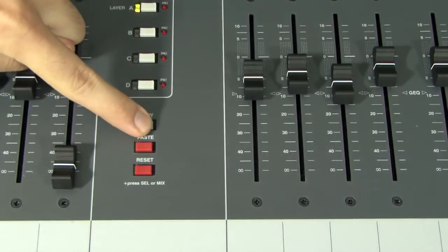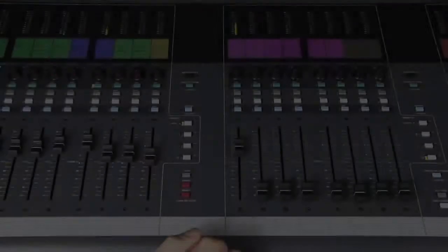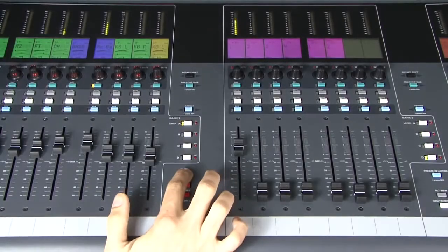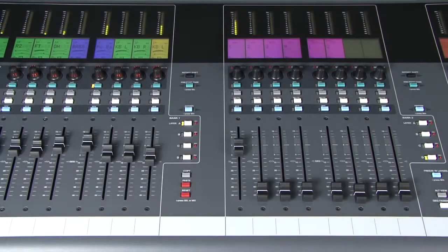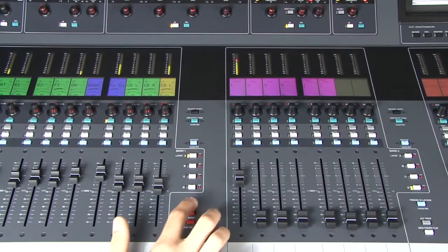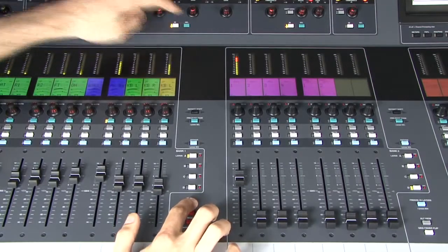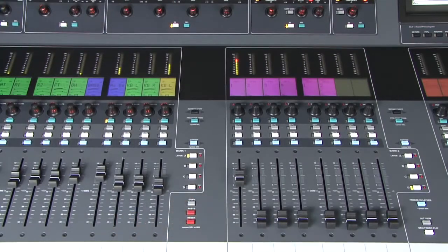Hold down copy. Pressing a channel or mix select key copies all the processing associated with the channel apart from the input preamp gain, pad and 48V settings, as the physical input is independent of the channel and may be patched to other channels. Pressing a processing block select key copies just the parameters associated with the selected block, for example a PEQ or gate.